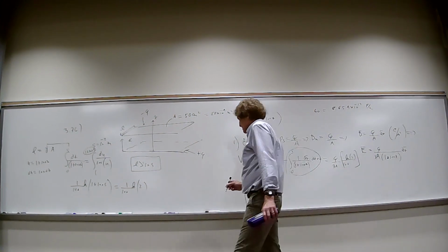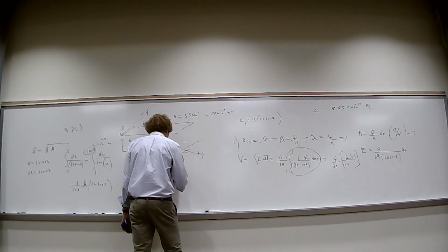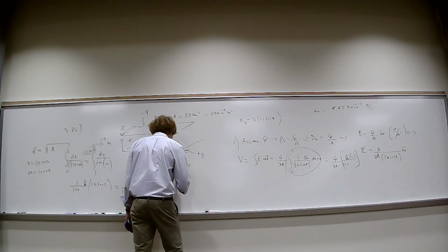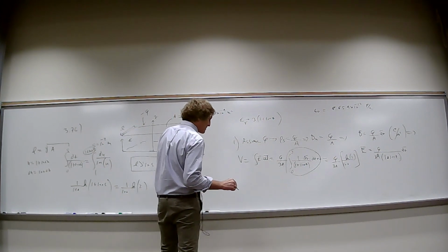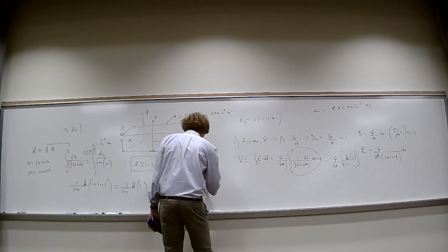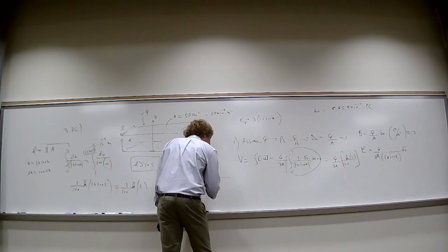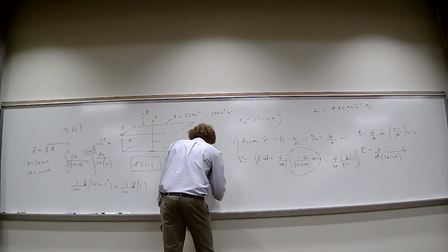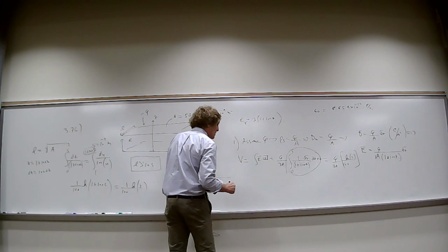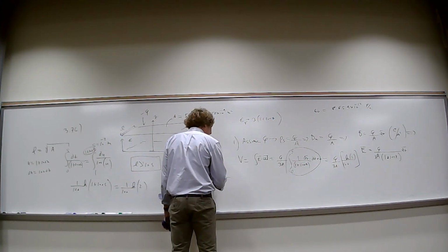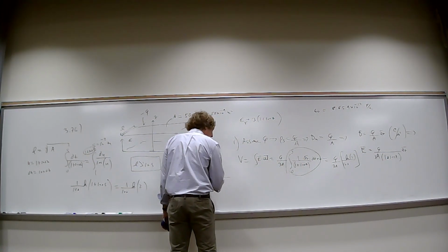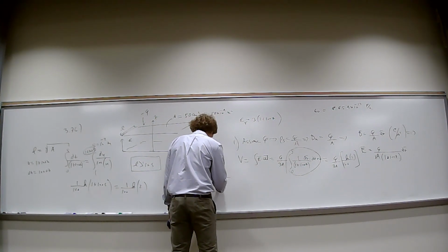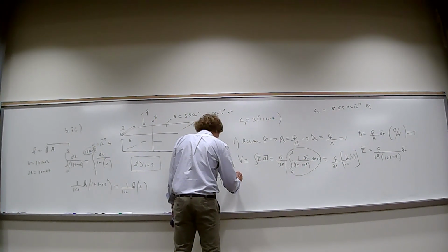And if that's the voltage, to get the capacitance, I know that Q is equal to C times V, or C is equal to Q over V. When I divide charge by voltage, I get 1 over natural log of 2, right? And then it's per A, so the A's go away. Well, it's times A actually, and it's going to be times 300. And that would be farads.